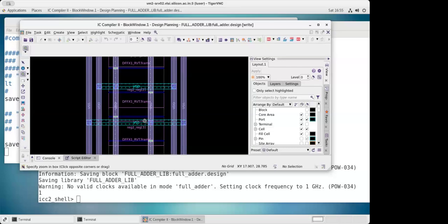Just do the pwd, so you are inside the scripts folder. You have to come out. Okay wait, just do the pwd. Now you are inside the wrong folder. Okay, pwd, enter. You are in the RTL to GDS, not in ICC2. Do the cd space ICC2, capital I, capital C, capital C, and tab. Press the tab button. Enter. Now source that file.